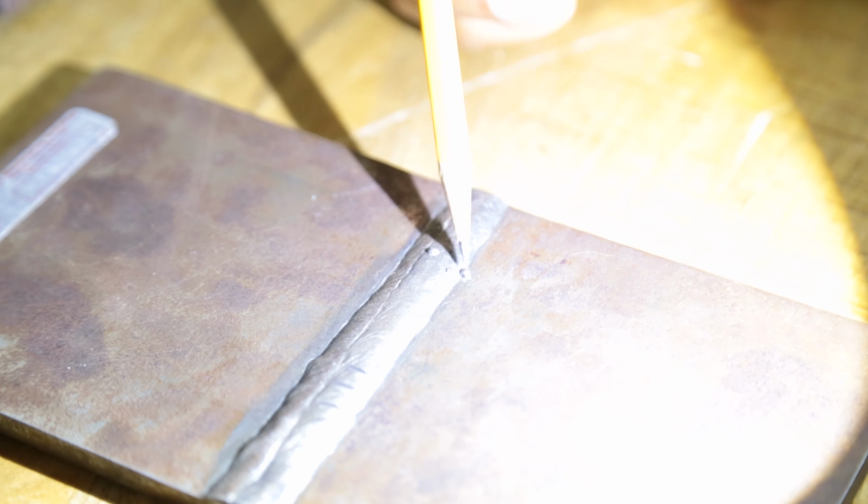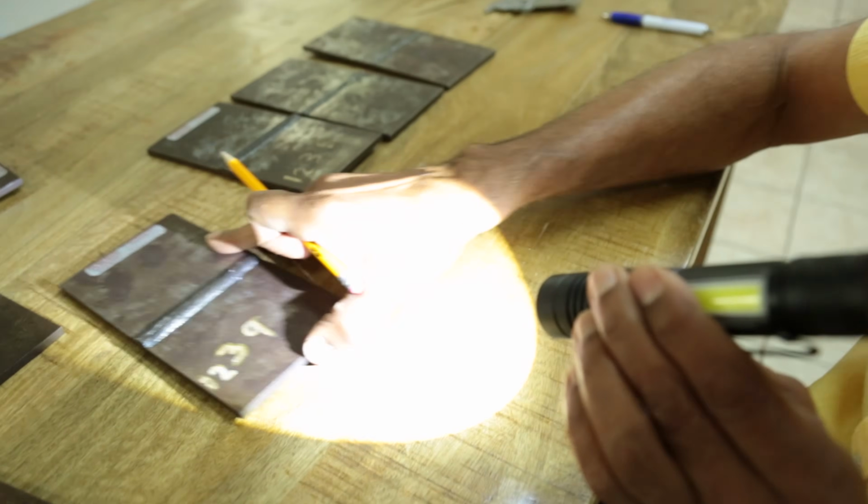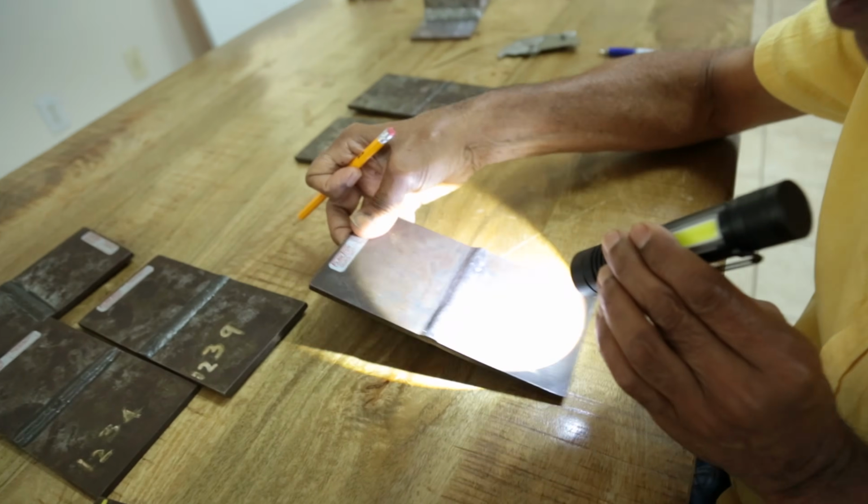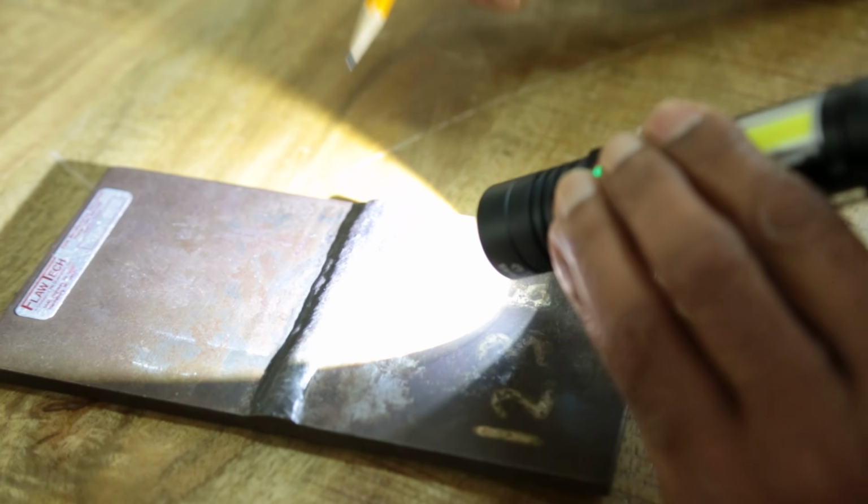So that, and then here we go. This is the weld spatter. Poor workmanship. That's not good to have. So, but I don't know if that would be acceptable or not acceptable, or you just grind it off. Then we have the undercut. So see, undercut is actually in the base metal. So that would be the undercut. And then if it says that anything more than, let's say, 1/16 is not allowed or whatever, you can actually measure it with this gauge, putting it like this and measuring the depth. And so from there you can say it's acceptable or not acceptable.